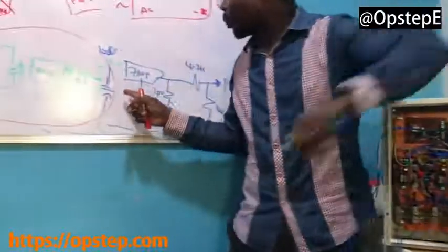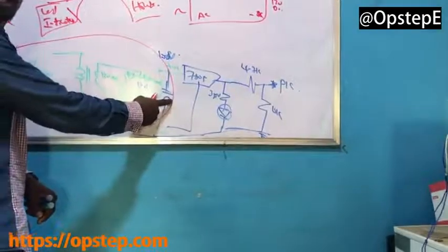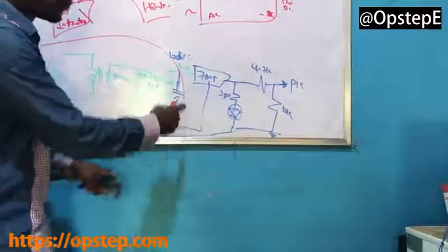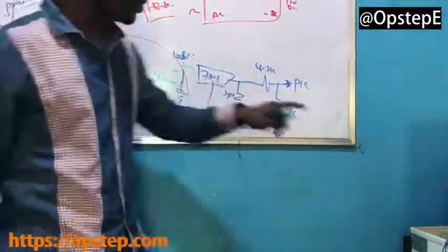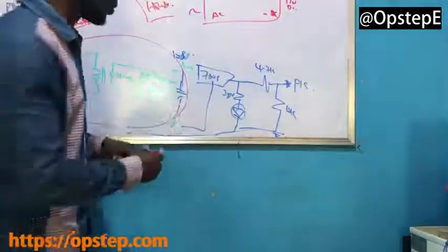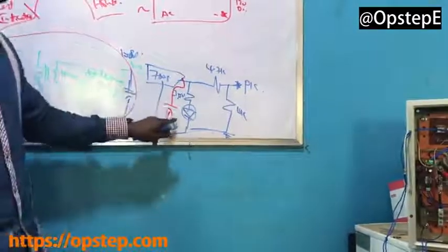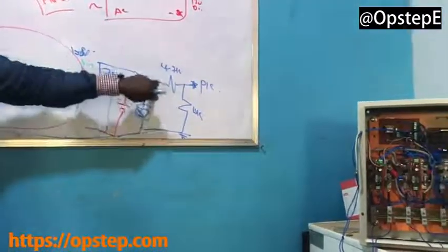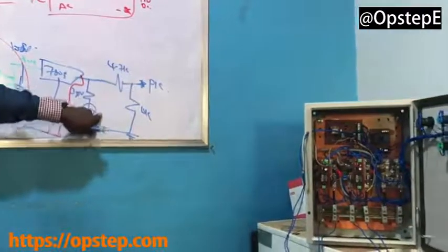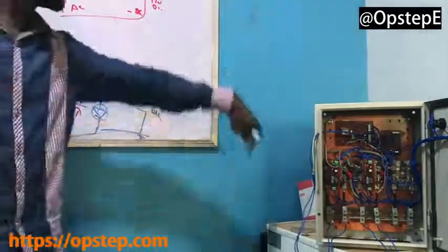From the output of the module is where you have this capacitor. Are you following it? After this capacitor, it went into a voltage regulator, which is the voltage regulator that you now have here. The output of that voltage regulator is filtered before it is sent through a resistor to an indicator, and then through a 4.7K and a 10K before it went into the PIC.